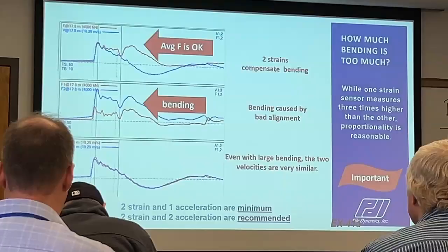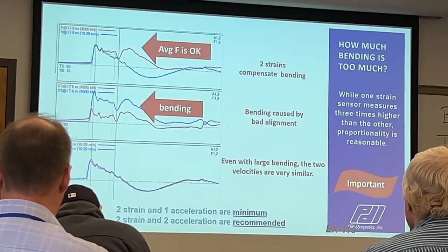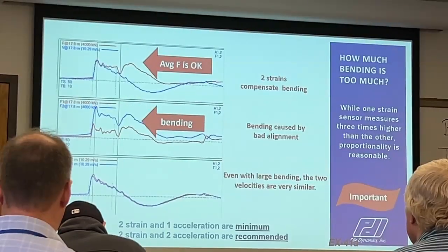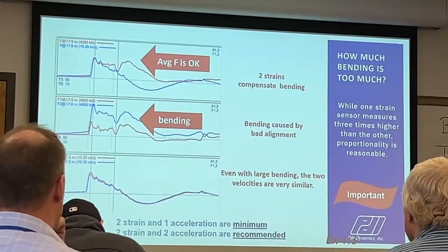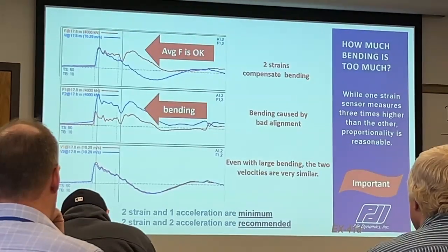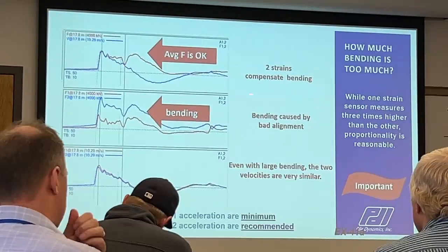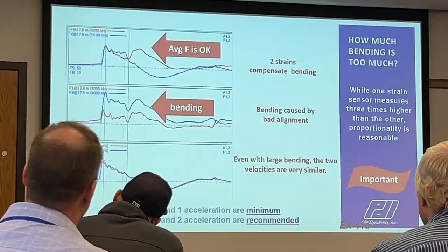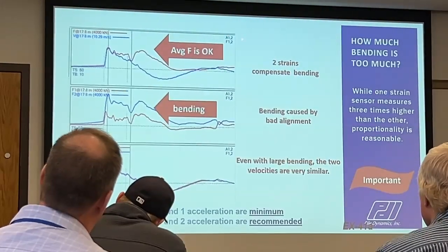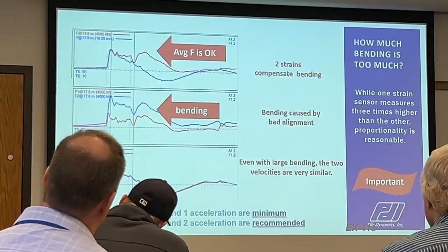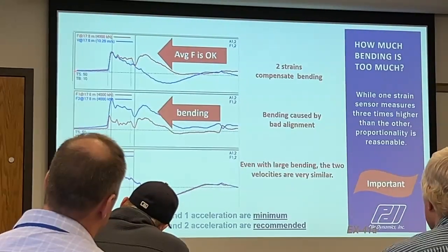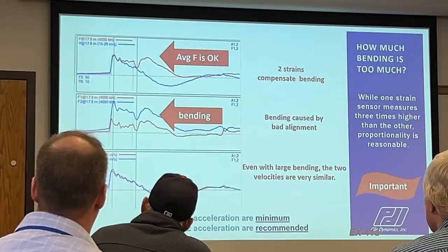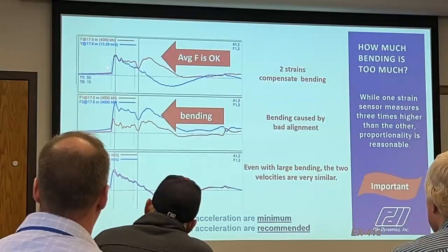So, a question that came up earlier, why do we do 2 strains? What should we do for 2 strain gauges that maybe are on a batter pile, or on the top and the bottom versus on the individual sides? We have 2 strain gauges, F1 and F2. Those are both included in the average. If we see both those numbers in the upper right, is this a diesel hammer? Yes, it's gradually rising, so this is a diesel hammer.